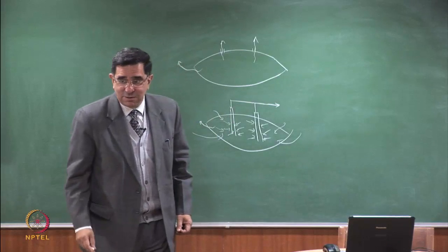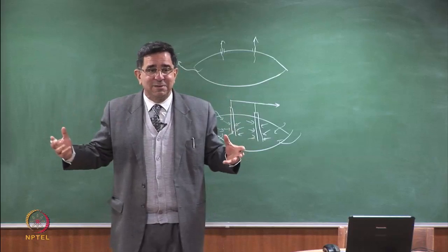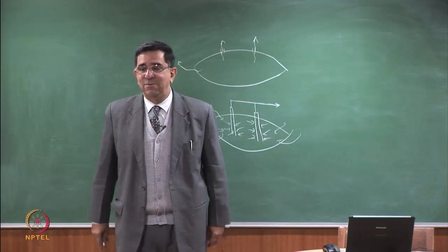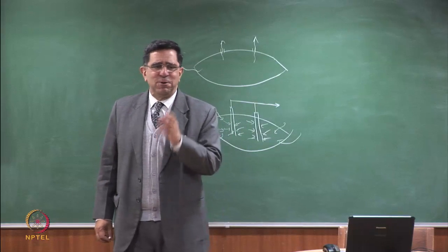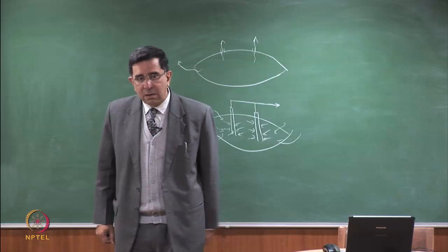If you apply too much suction, what will happen? Gas is not being produced. If there are any leaks in the system, air will start coming in from the side and from the top. So you can't produce more gas, you can't collect more gas than what is being produced inside the waste.